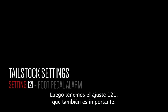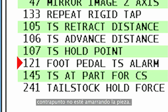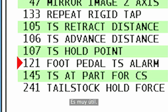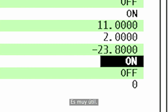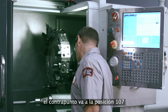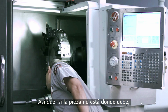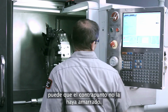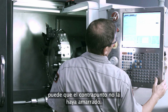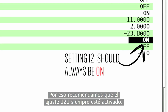Next, we've got setting 121. This is also important. When you use the foot pedal, setting 121 warns you when the tailstock is not clamping the part. Pretty handy. With setting 121 set to off, the tailstock moves to the 107 position, but it doesn't check if it's reached the part. So if your part isn't in the right place, the tailstock may not actually be clamping the part. That's why we recommend setting 121 should always be set to on.